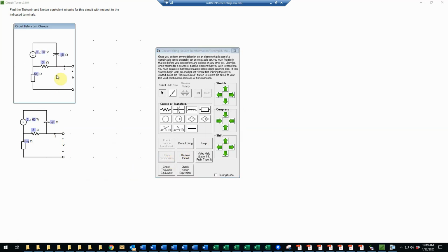And now it shows me the last valid step that I took. And now you might say, well, are these two, for example, in series? But you have to remember that even though they might look like they're in series, they're not, because there is some current I. We're going to connect something out here. That's the whole reason of making this equivalent circuit, is so we can connect it to something. And therefore, there will be a current I here, which means that these two things will not have the same current as they would if I were 0. So unless we're doing open circuit voltage, these things are not in series. Okay, so because of that, we cannot combine those, and we can't combine really anything else here.